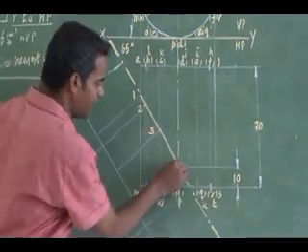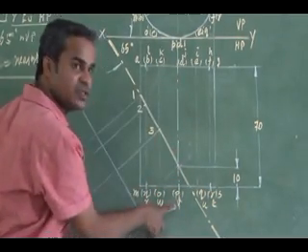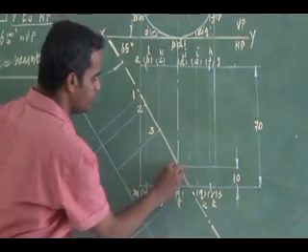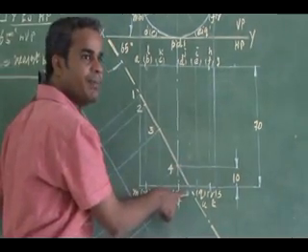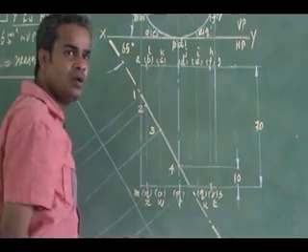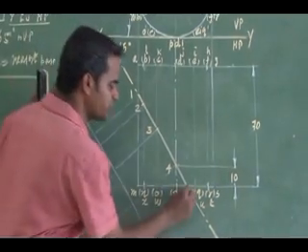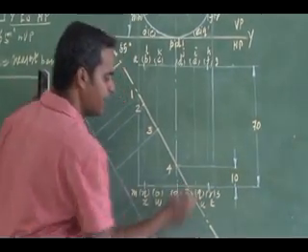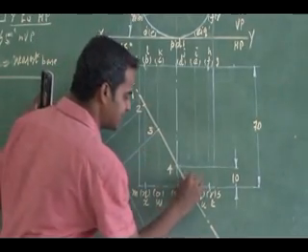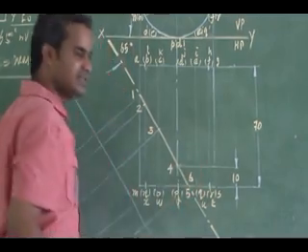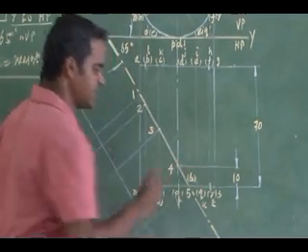Then you go along the cutting plane, it cuts the middle generator, that is visible generator VJ. So that is my cutting point 4. Then immediately it goes to the base. There I will have 2 cutting points. One is visible, that is 5. Another one is hidden, on the same base itself, that is my 6, hidden 6 on the base itself.